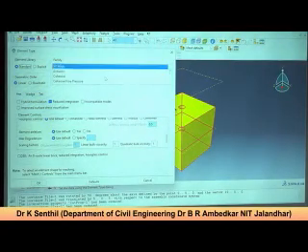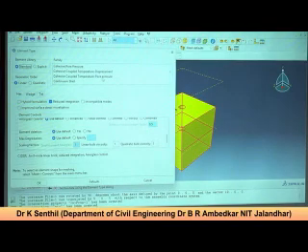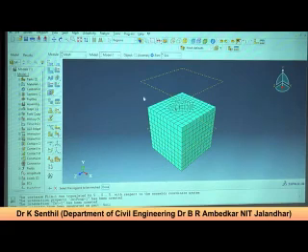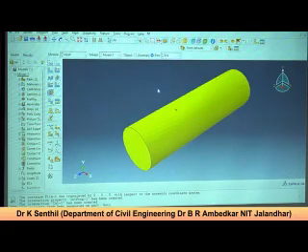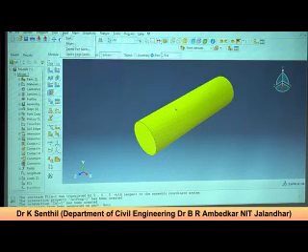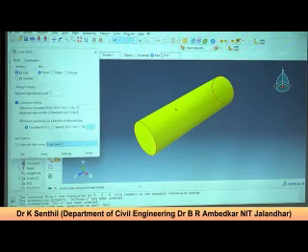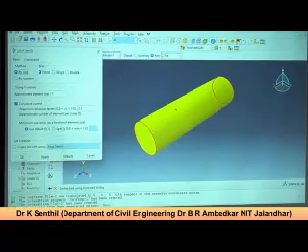And you can see here various families like 3D stress, acoustic, cohesive. So you can select accordingly. Now it's done. Now we go to the meshing, region wise or part wise you can do meshing. That's all. Okay, now let's go to the pile, and in the same way you just seed this. Seed is nothing but edges. You have to create the nodes. The objective of these nodes is to define the basis for solving the unknowns.